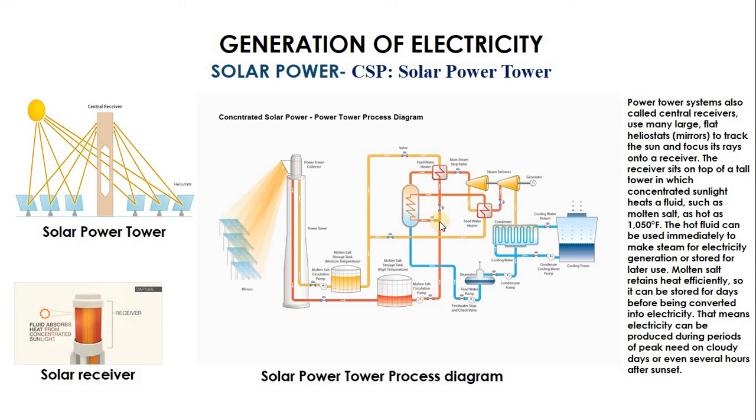As you can see, the working fluid comes here, it goes through here, and if the water fills here, the hot working fluid in this pipe boils the water, generates steam, and then drives the steam turbine to produce power. This arrangement here is to further heat the steam. So after the oil comes here, it boils the water in this chamber and produces steam.